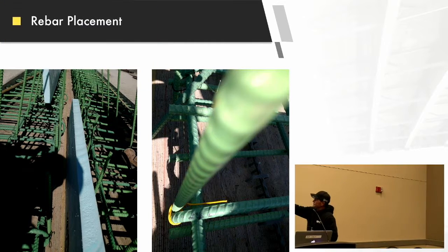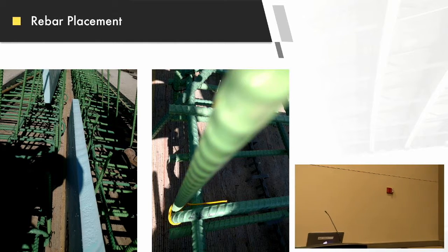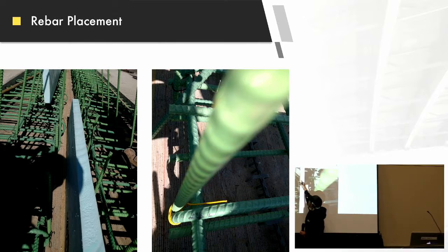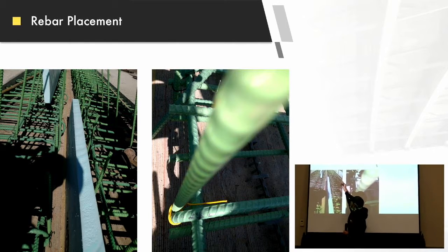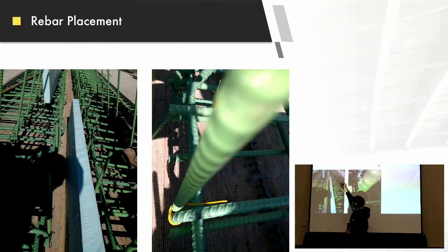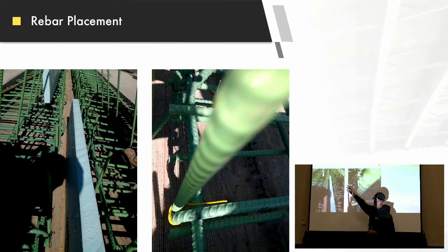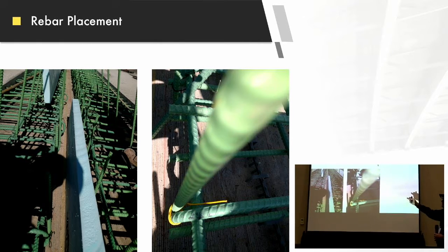These are some pictures of some places like here. They've got their foam. This is a really tight structure. This is on a deck. We've had to redo the parapet and the edge of deck. They've epoxied their bar into the existing deck, and it's obvious that a few of them didn't get drilled far enough and put in far enough.